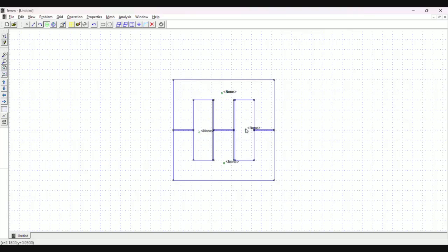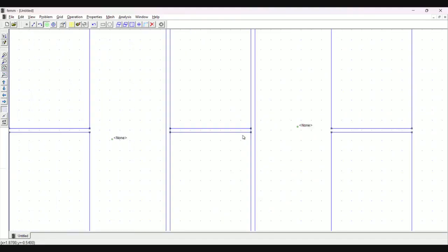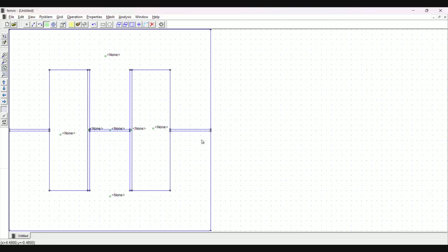air. Let us see. We'll zoom in. Yeah, this is air. And see, I wanted to assign copper here. So if this is open, this hole will become a single material. So I cannot assign copper for this. That is the reason I was closing it.